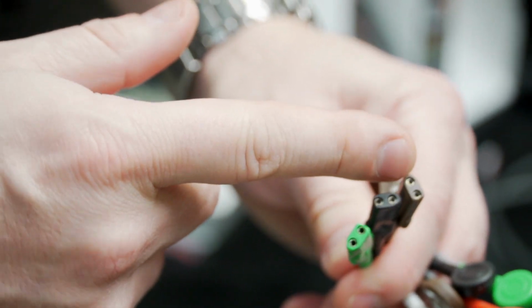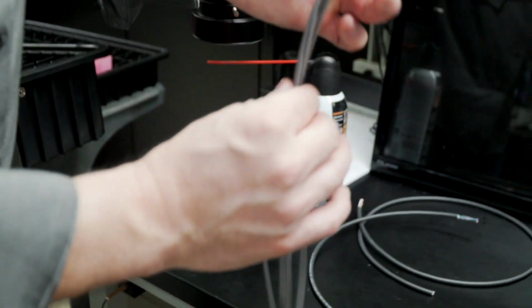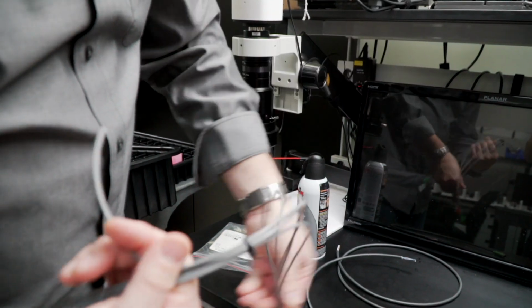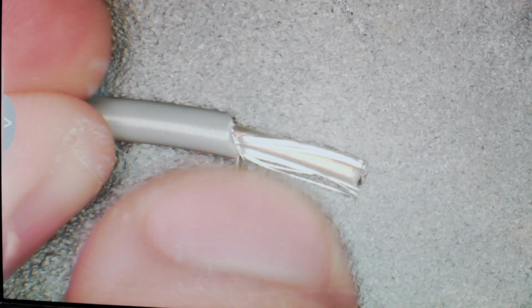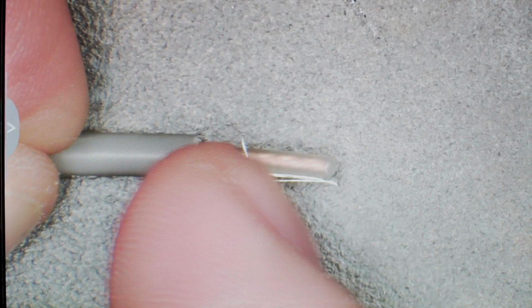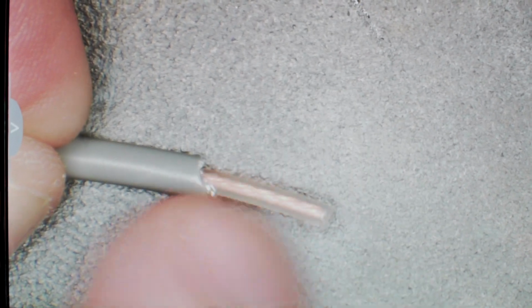So one of these leads is actually relaying the signal information, and the other lead is used as an antenna. So the shielding for this cable, if you look in here, you can see that the cable has the metal insulation there. That's what we use for the antenna. It does have the center conductor wrapped in that plastic protective sheathing. That's what actually carries the signal. So during the process, we're going to trim away the antenna portion, which we're not concerned with, and we're going to focus in on the signal portion.